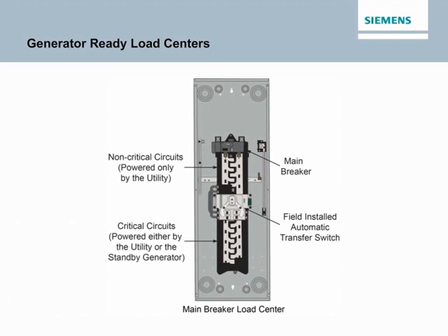In order to accomplish this, an automatic transfer switch or a manual transfer switch must be installed. The switch, along with any branch circuit breakers required for the application, must be ordered separately. However, installing the load center without the transfer switch is a cost-effective approach for new construction when a generator will not be initially installed. This approach allows the wiring needed for standby generator operation to be completed during initial construction. At a later time, the homeowner can install a standby generator without the cost of rewiring.